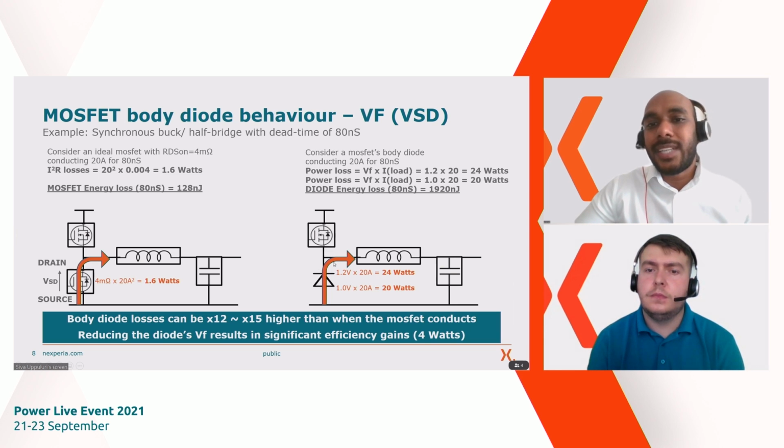Nevertheless, given the limitations on how small the dead time can be, it is important to choose a MOSFET that has a lower VF compared to what you can get elsewhere.